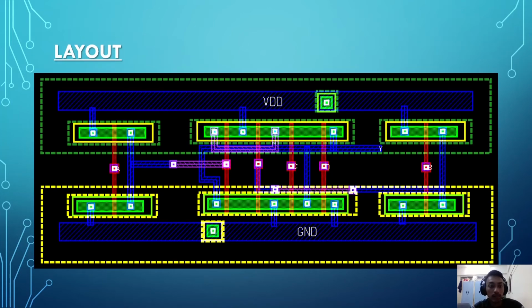So this is the layout implementation from the stick diagram. This is the final layout. It is different from the stick diagram as we compacted the size. So we combined the inverters here to reduce the size of the layout.